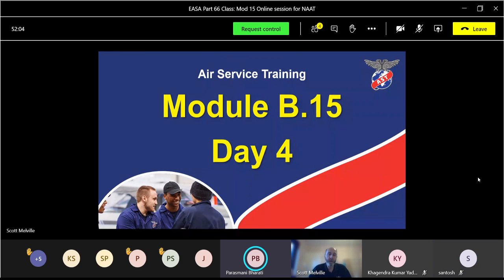If we get high pressure, which capsule is going to move? In which way? Is it going to expand or contract? Contract. Yeah, it's going to contract. So the P0 is going to contract, which means it's going to shrink, which means it'll lift the servo line up, which will close the servo line, and then increase servo pressure to increase fuel output to stabilize depending on the RPM.